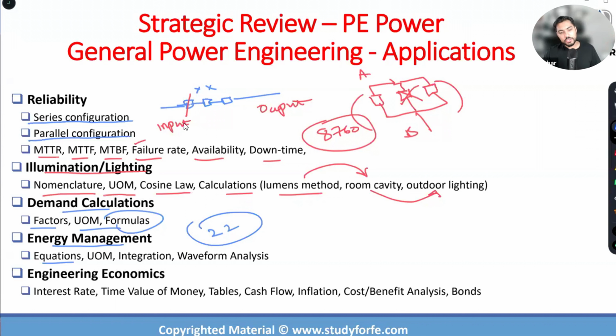So you've got to make sure that you have sound fundamental understanding, and waveform analysis is the name of the game when it comes to demand calculation and energy management. If you're good with straight line equations, and we've done several practice problems, right? If you don't rely on a plug and chug approach of finding the area under the curve, if you're able to divide, find the regions of operation, and go about solving it in a methodical, systematic, and proper way, then these problems are not that difficult. You just have the layer of understanding that you have to throw on top of waveform analysis, which is the terminology.